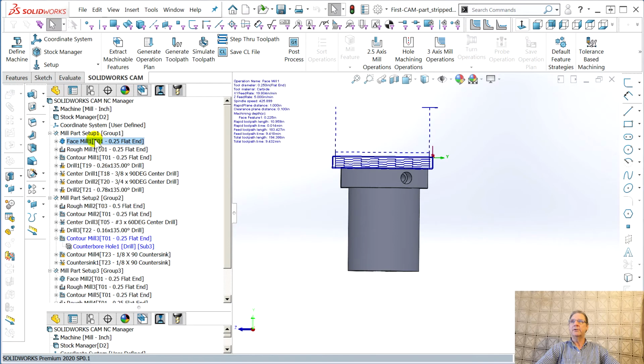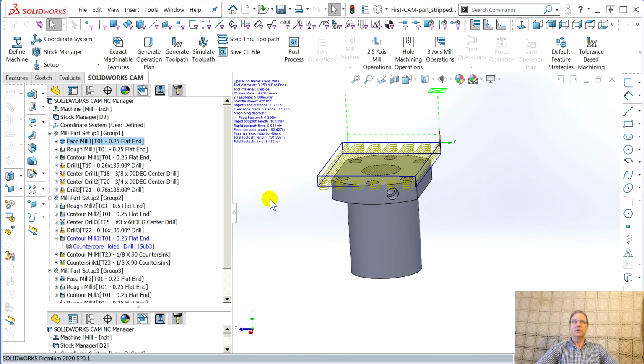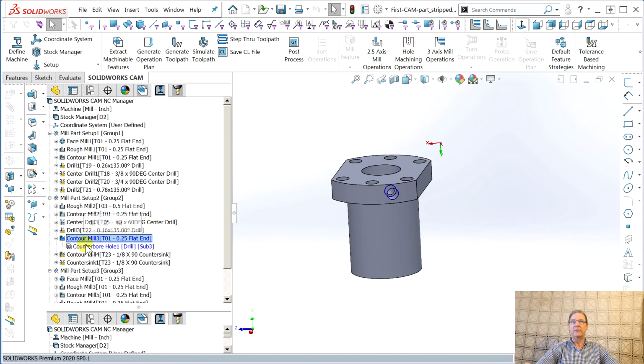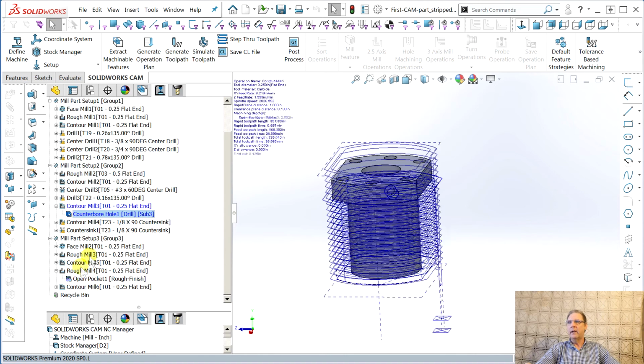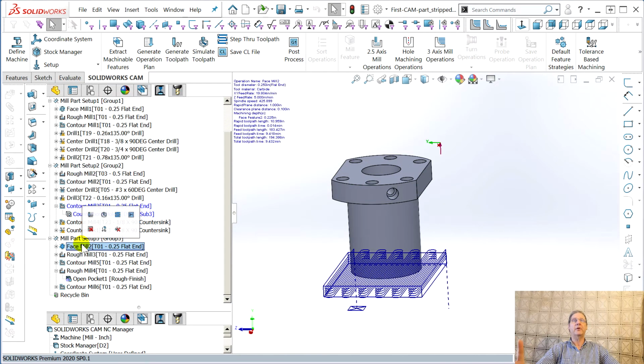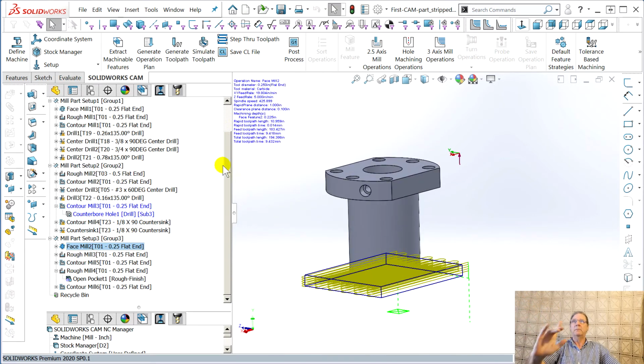So this is cool. They're smart enough. If you have that checkbox in the SolidWorks CAM tools, feature recognition, if you have that checked, it puts face milling first. There's that contour mill, something about that it didn't like, I don't know why. And then mill part setup 3, face mill first. Good, this will save us a few crashes. So now, without touching anything, it's obvious to a machinist that this won't work. You machine through the vise, but there's worse problems.